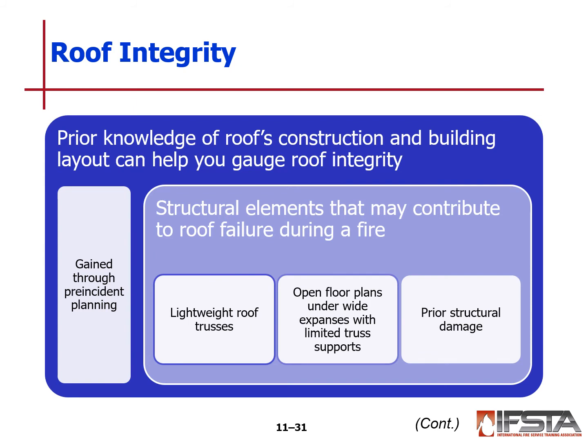Integrity of our roofs. This is something that we don't put firefighters on roofs as often now as we used to, but we need to know some things. Prior knowledge of the roof's construction and building layout can help you gauge the integrity of the roof. Is it stick built? Is it truss? This information can be gained through pre-incident planning. Sometimes you can look at the outside of the structure and tell. Sometimes the homeowner may know what type of roof has been installed.